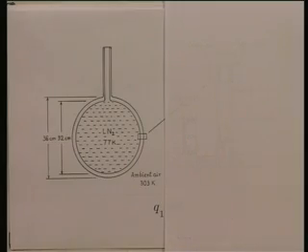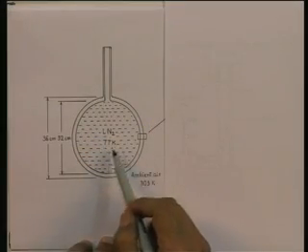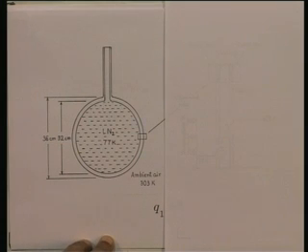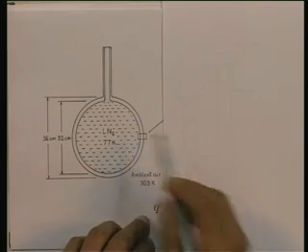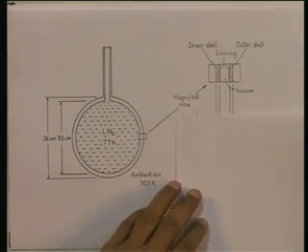All right. So, cryogenic liquids like liquid nitrogen are stored in spherical containers. The sphere has the advantage of providing the smallest area for a given volume, and so it is advantageous to have a spherical shape. You want to, after all, reduce the amount of heat flowing in, which will make the liquid nitrogen evaporate. You are told the ambient air is at 303 K and the liquid nitrogen inside is at 77 K.